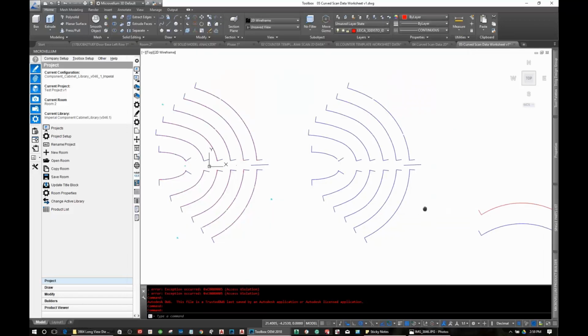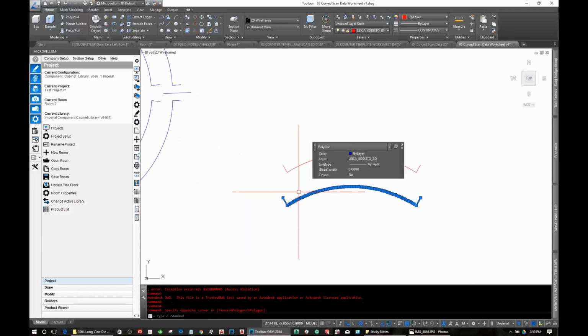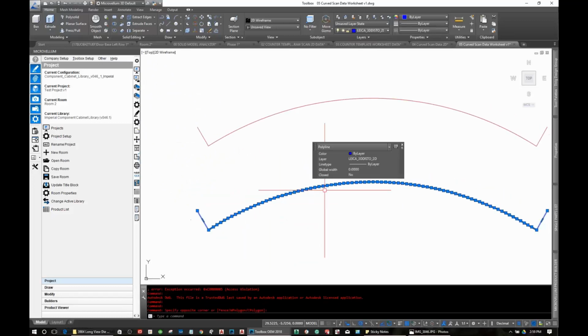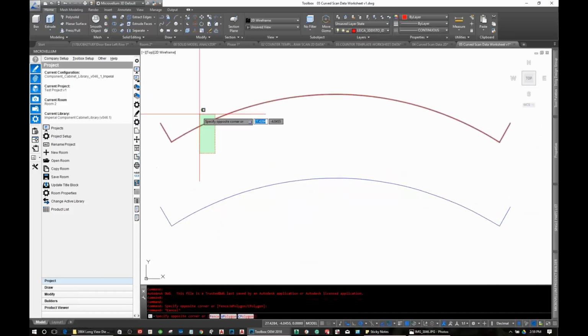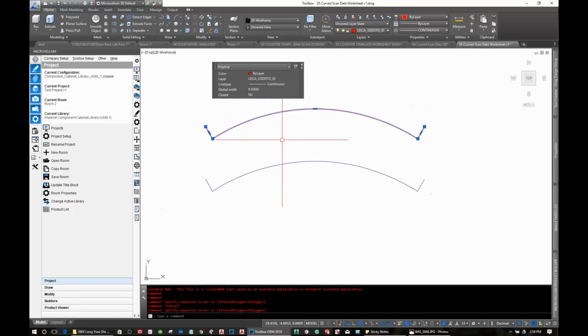With the extruded product builder, you could take the scan data, and this is what I did here. I isolated, so each one of those points that you see is a measurement, and then I superimposed a radius over top of that, and now I can just bring this into the solid model and go through and have my file right from there.